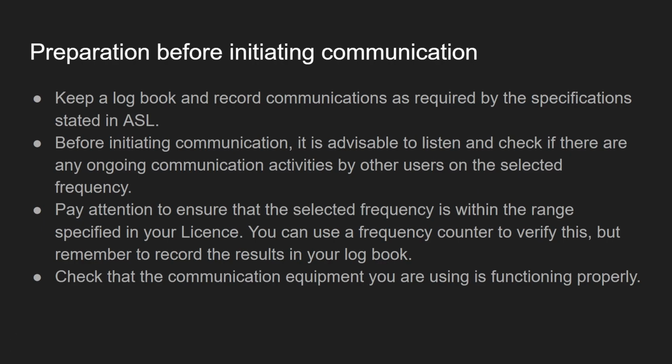Check your equipment if it is functioning properly. Yes. So sometimes maybe we will also connect it to an SWR meter, a standing wave ratio meter, to measure if the antenna can transmit the signal in a good condition or receive the signal in a good condition.